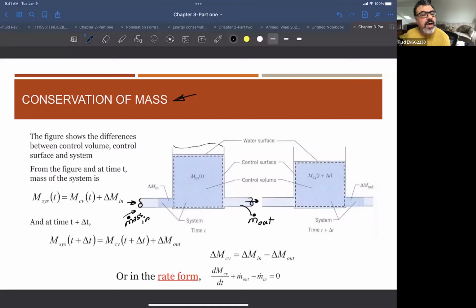What part of the math? It's not math. It's an understanding of the fluid flow in a system, right? We know that because of the viscosity of the fluids, when you have a fluid between plates or a fluid in a pipe, we expect a maximum velocity at a certain point that is far from the wall. In the pipe, the farthest point from the wall is the center. So that's why the velocity is maximum at the center.